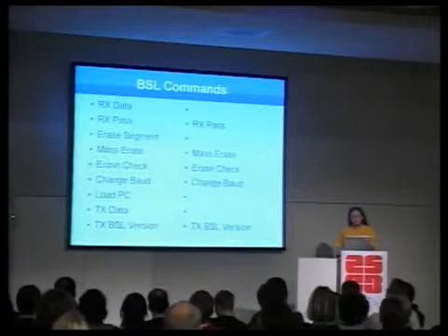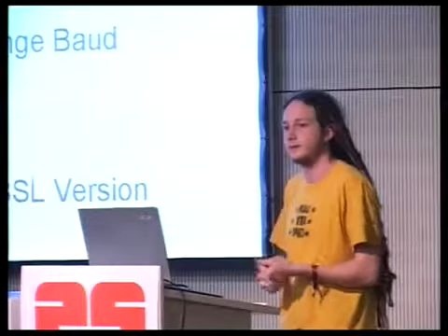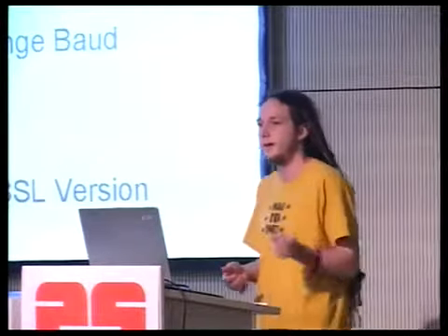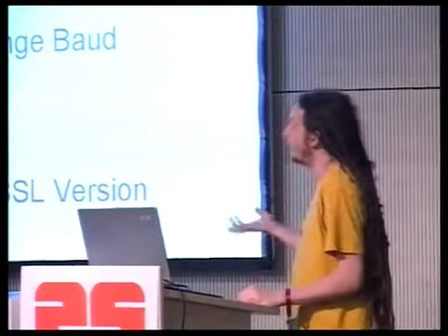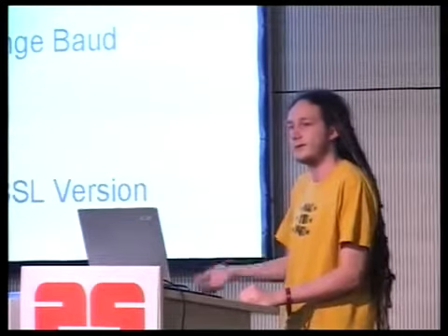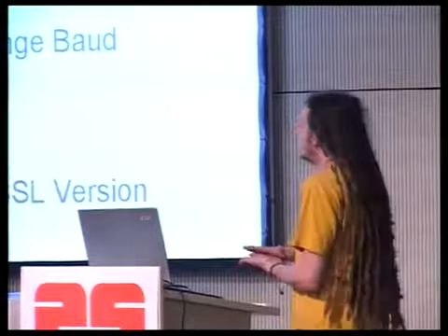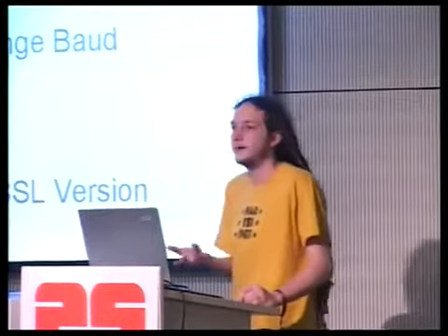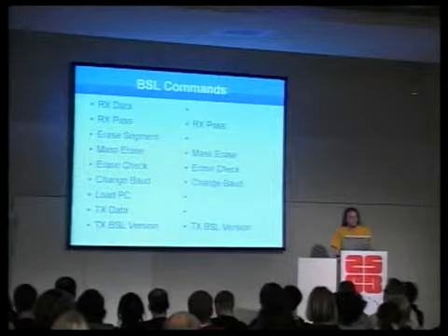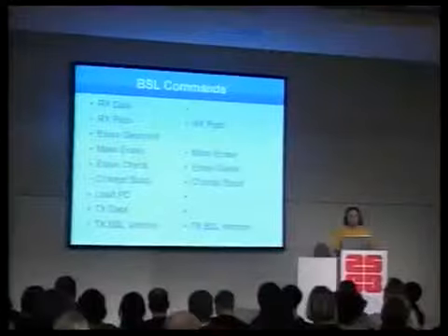The reason for this is that if you could tell it to transmit data to you, then you could just have it transmit the password. Or you could dump a copy of the firmware of the chip and then start making counterfeit boards. So commercially, if one firm got a board that belonged to a competitor, instead of spending the time to design it from scratch, they can just photographically copy the PCB layout. And then, if not for the protection mechanisms, they could also copy out the firmware, load that firmware into the new board, and sell it as if it were their own. And by changing the board layout and keeping only the firmware the same, it can become difficult to prove that your competitor has stolen your firmware.